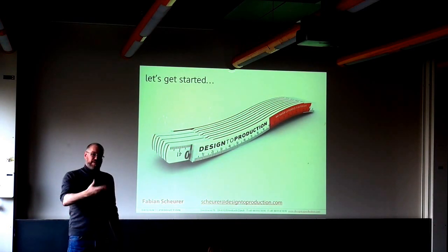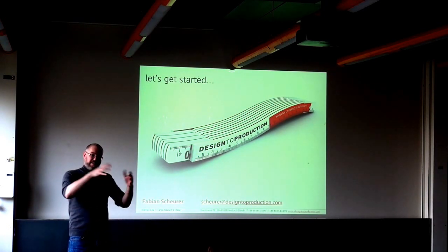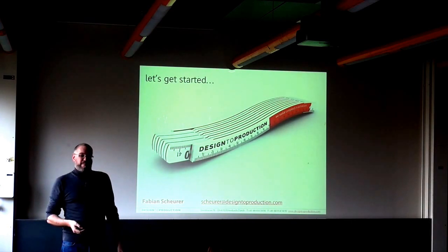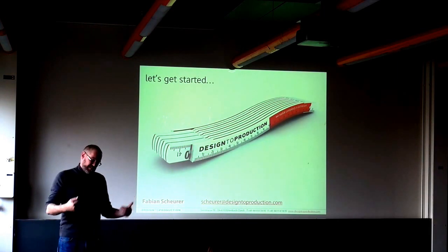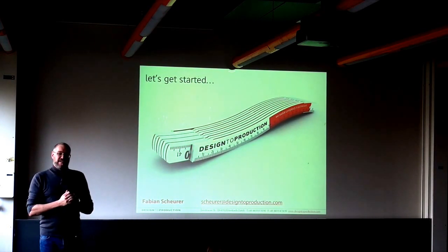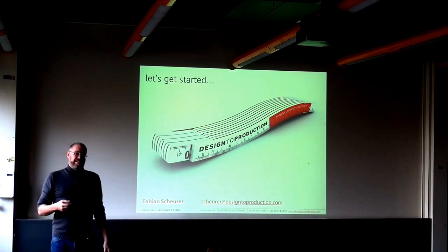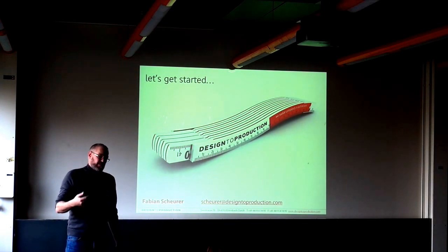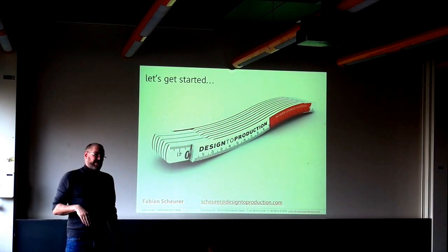If you just have the volume object of this thing, you'll never see that. So you have to actually take a step back: what do I actually want to find out? What could be the error that is in there, and how can I find that? Oh, I come up with a checking routine. I run the script once, it generates all those, and I see it instantly. And this is sort of the next abstraction level on top of actual parametric modeling, is to step back into the testing also.